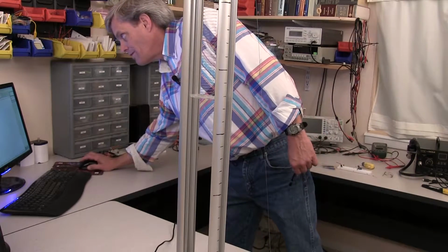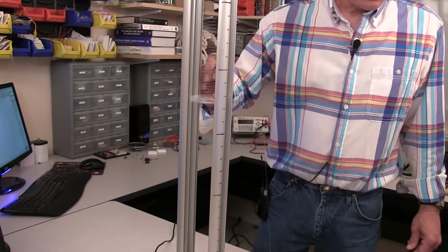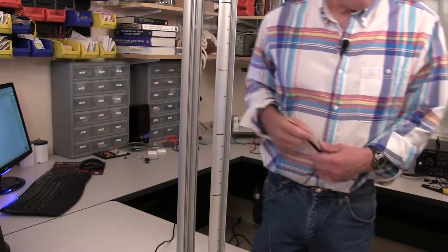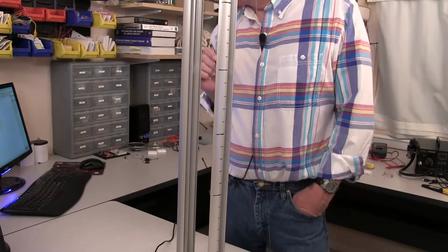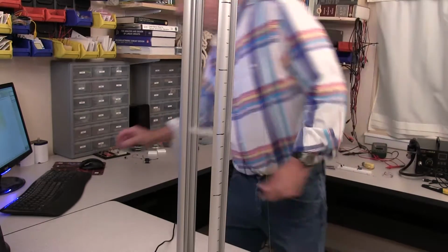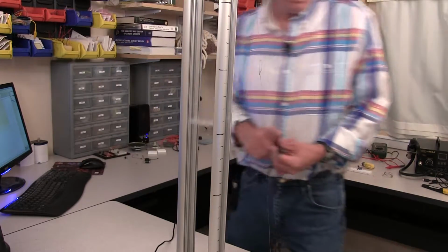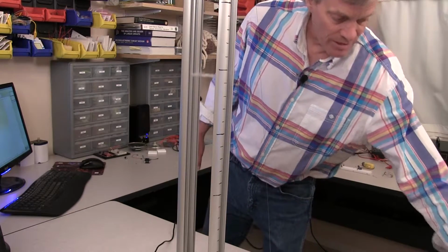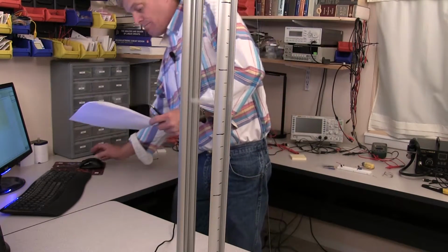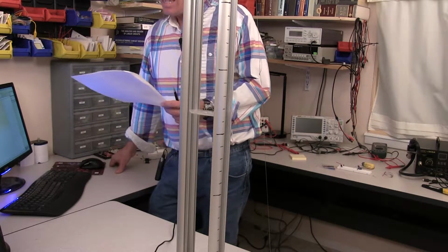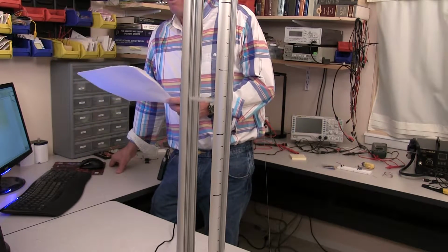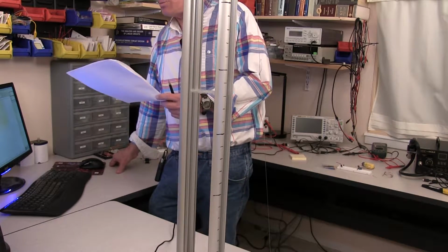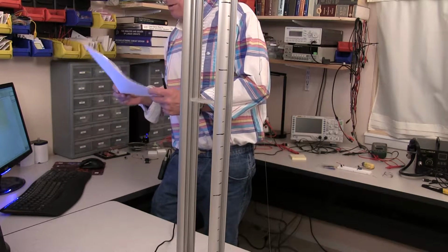I'll start the oscilloscope acquiring data, stretch the spring, and release the platform. The platform moves up and down, and the voltage out of the sensor tracks this motion. Unfortunately, the output voltage levels are small, only about 0.2 of a volt over the entire range of motion. If the entire range of motion is about 15 inches, this means that the sensitivity is about 0.2 divided by 15, or a little over 1/100th of a volt per inch. This will make it hard to actually measure small displacements since the related voltages will be so small.